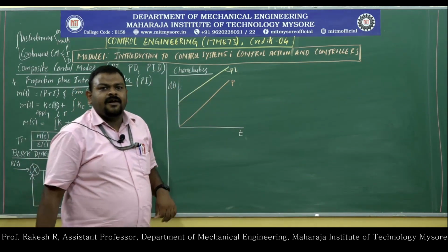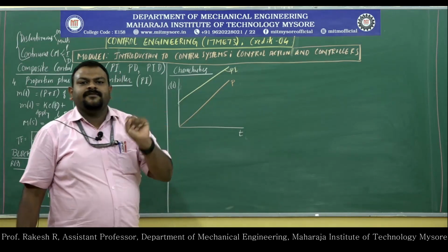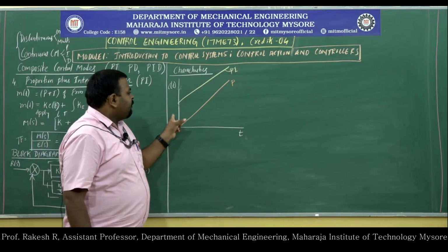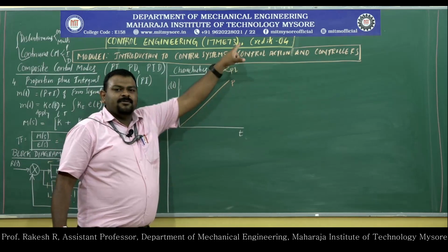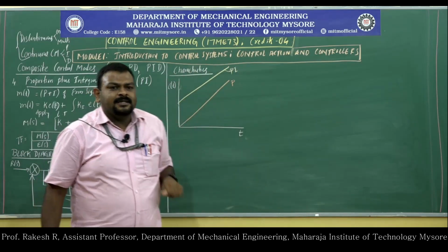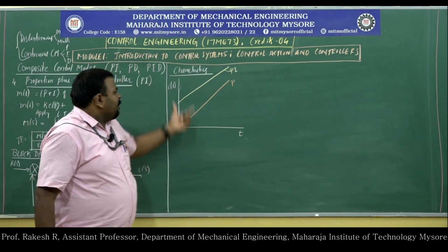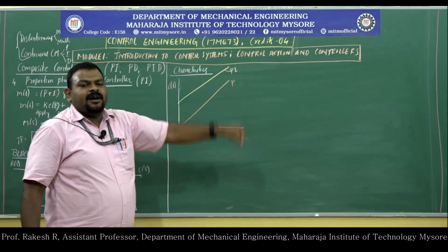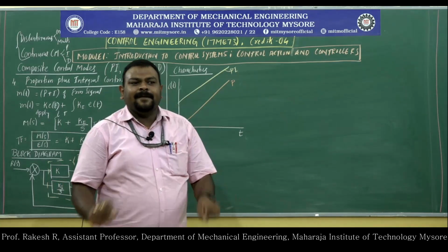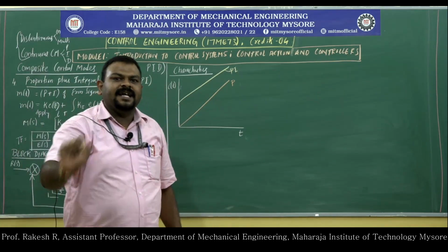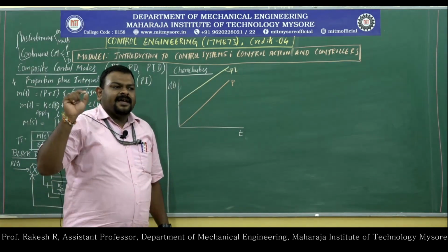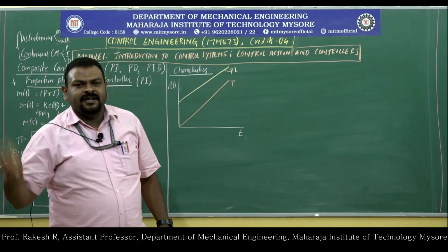The characteristic of the integral part is slow response of the system. So after some value the response will be slow. That is undesired in the case of a practical system. So in order to avoid this, we will integrate proportional integral with a proportional derivative controller, that will be exactly the PID controller.